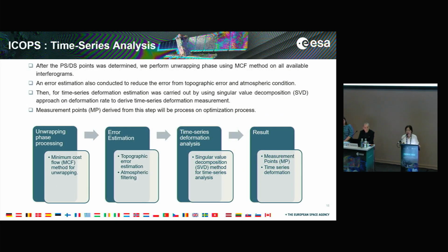After the PS and DS points were determined, we performed phase unwrapping using the MCF method on the available interferograms.